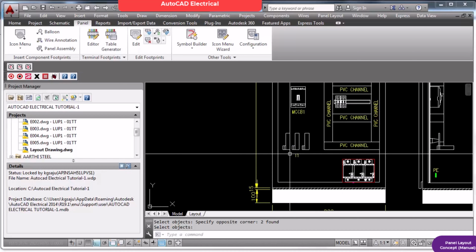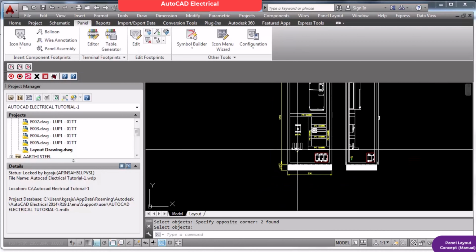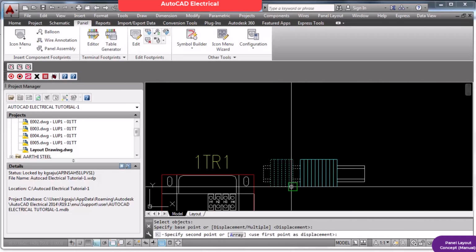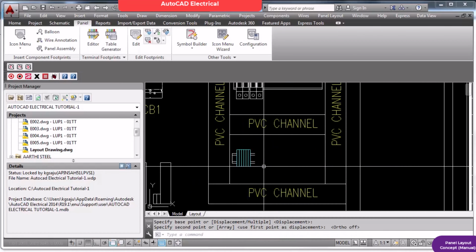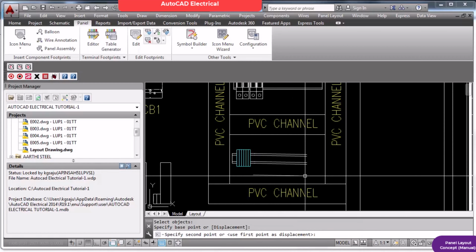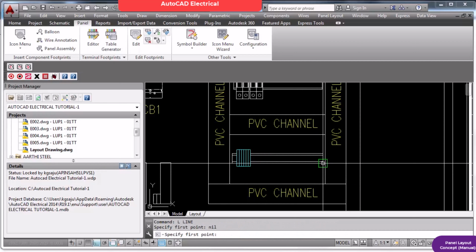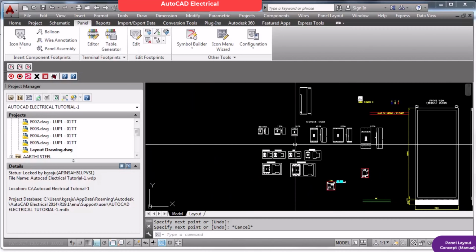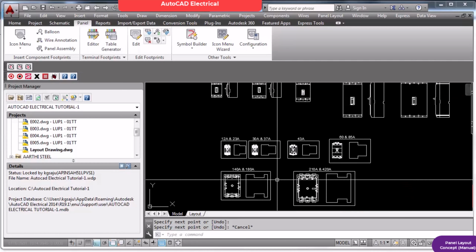And of course you can do the dimensioning, especially for these major things like the distance between the bottom and the termination. Many customers will ask you to give a clearance of 250-300 mm minimum for power cables, and if it is control terminals, you can adjust a little bit here and there. If I want to keep some control TBs here, everything should be in one sheet so that you don't have to look for the blocks. And in fact, if you keep a proper library, you can bring these components directly from there. I do it that way.